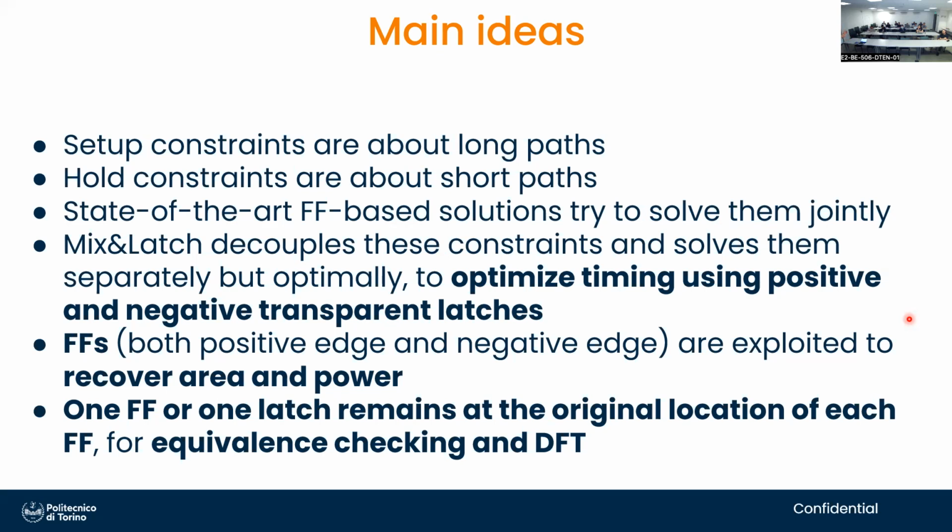And very important, as I said, for every register that we had at the beginning, there will be a register in the same location at the end, enabling the use of standard tools. Very important because we don't want to create our own tools. We built an optimizer that drives existing place and route tools from Synopsys, Cadence, Mentor to do the right job under our constraints. But we only compute those constraints. We don't do the layout, we don't do logic synthesis, anything like that.